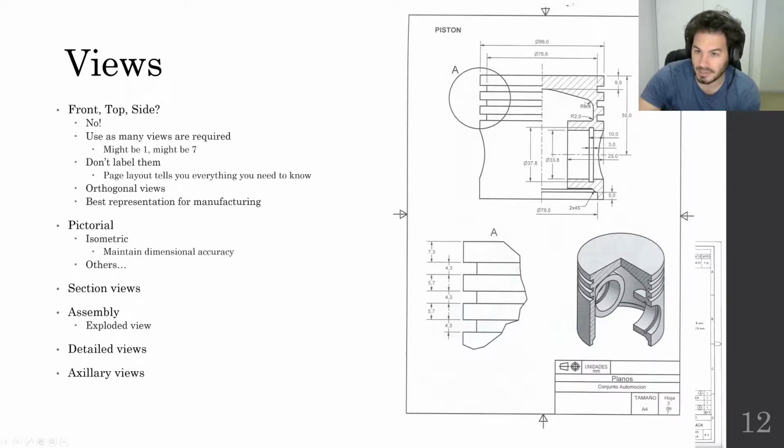And this is why often you make lots and lots of sketches. Because you started drawing it, and you realized, oh no, I really should do a partial section, or I really want to chuck in an isometric, or no, I've run out of space trying to draw this. What I should do is draw it smaller and then put in a detailed view. Whatever. You kind of just learn these things as you go. So yes, some planning will definitely help you, but again, sketches are cheap. So have a quick go at it, see if it works.